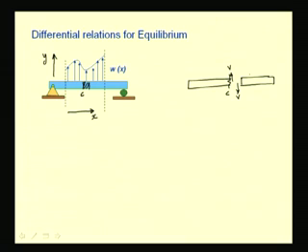Now, let us take a section at a very small distance, say delta x, on the right hand portion of the beam, and if we consider the free body diagram, we will have a shear force which has changed also incrementally.